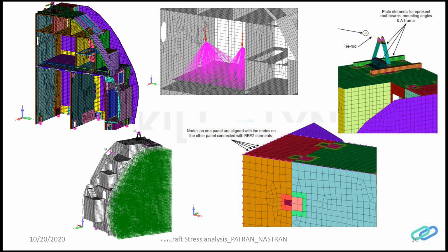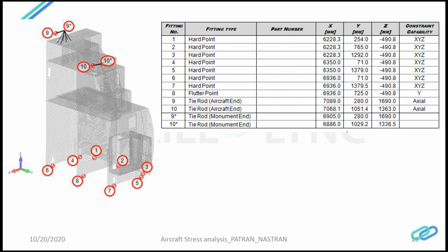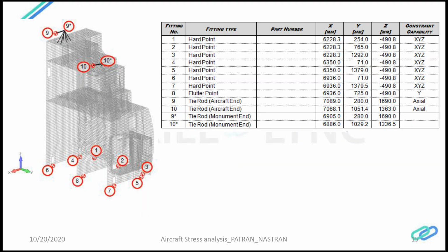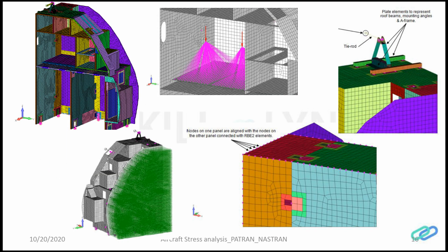And then coming to the upper attachments and the strut, as I mentioned earlier, this is one model. There is another model where I modeled the upper attachment using 2D elements, and then the final strut using the CROD element. Whereas in one other model I modeled the entire structure as bar elements, and then the final rod using the CROD element.